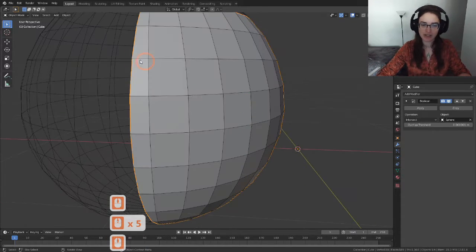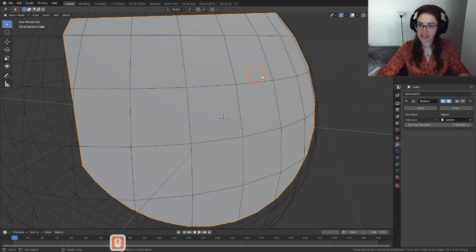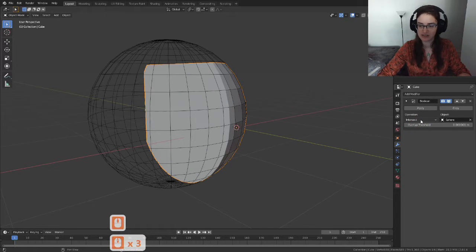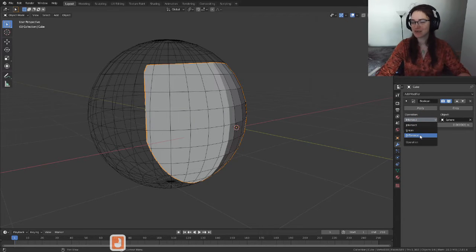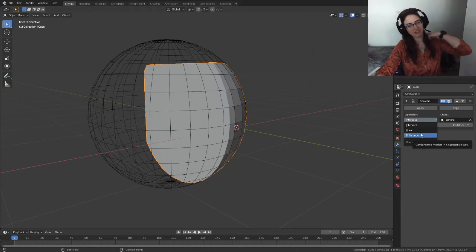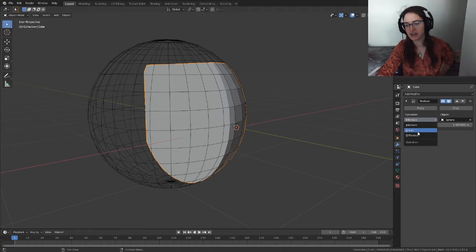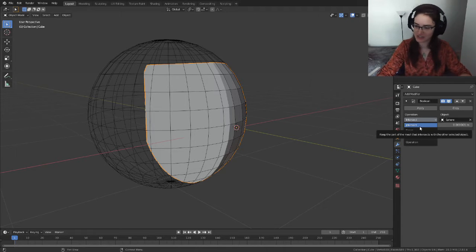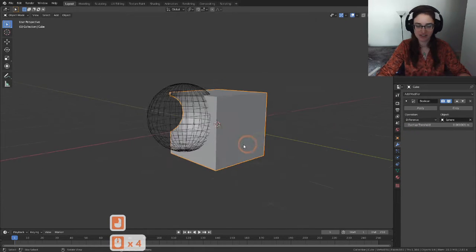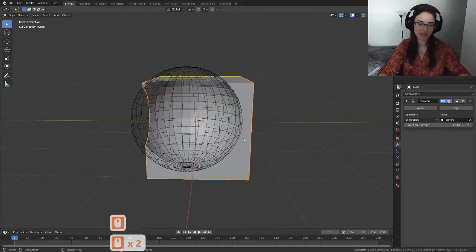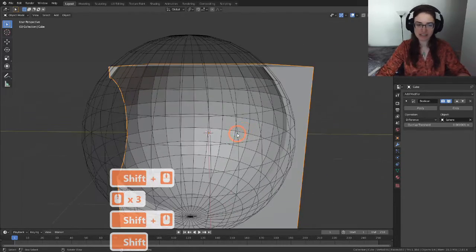So anytime you want to use a shape to cut out a shape, that's intersect. For now, we're just going to use difference. You're most often going to use union or difference. I haven't had the big brains enough to use intersect, but it'll have its uses once you become more comfortable with using Blender. So back to difference.